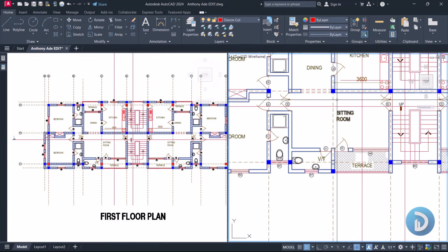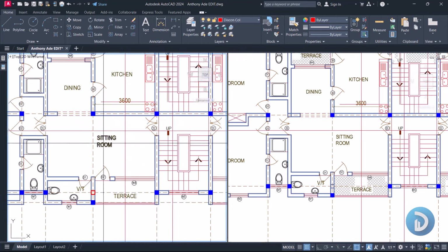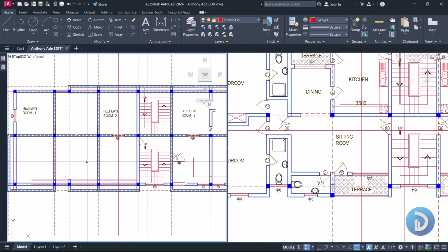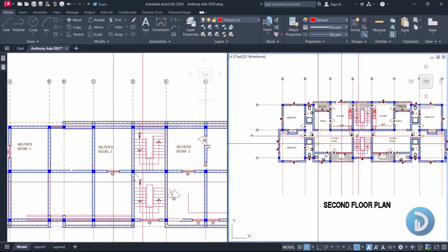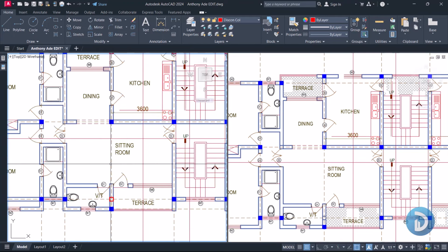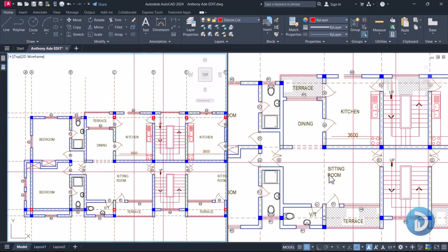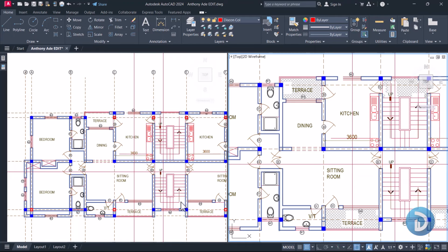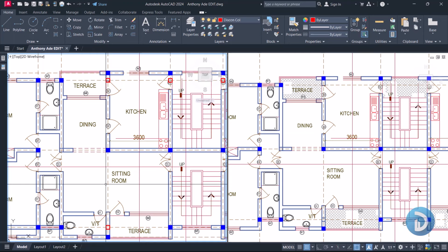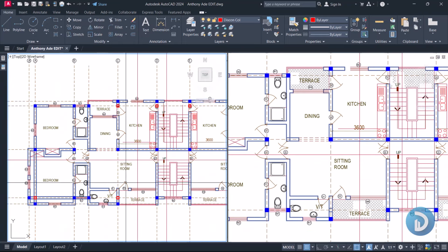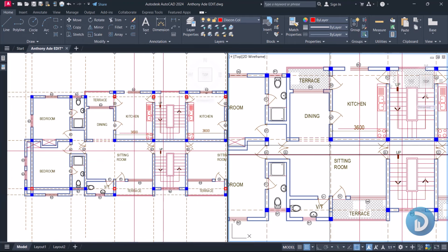So like we said earlier, in order not to be seeing a beam here, because we cannot continue the same beam arrangement on grid line C. Okay, we can't continue this same arrangement on grid line C, because if we are to push that same grid at this sitting room area, so if someone is sitting at this sitting room of the first floor, the beams that are supporting this grid on the second floor will have to drop. So whosoever is sitting here will get to see that drop beam straight into the sitting room. So this is not a very good practice. So we can as well make further modifications to this first floor plan in order to carry whatever is coming from the second floor.